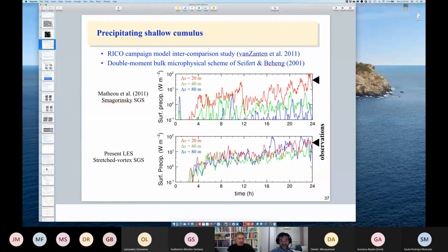I see. So there is a physical criterion that locks your numerics. Yeah. So you run the simulation, and the LES says the unresolved TKE is about 30% of the total. In that case you must say, okay, this is not the regime where my simulation will produce converged results, so I need to bump up my grid resolution.